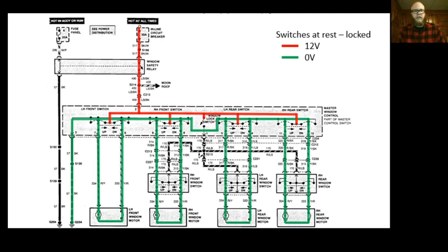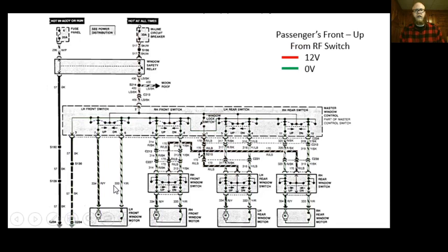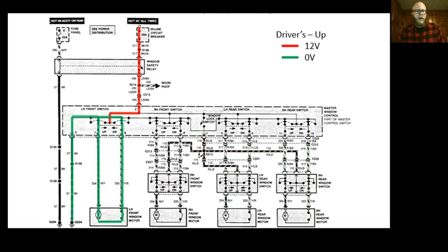in his toolbox, and he would go and he would do this. He would be like, okay, I only care about this circuit. So let's go all the way back. So I only care about this circuit, and the power window doesn't work. So we'd go through and he'd color like, so this is where power should be, this is how it should be grounded, or it won't roll down. So how should it be set up? Okay, now it's really simple. All I need to do is make sure I've got power here and ground there. And if I do, then the only thing that could be wrong is the motor at that point, right? So any tool in your toolbox is useful, even if it's just a color pencil.